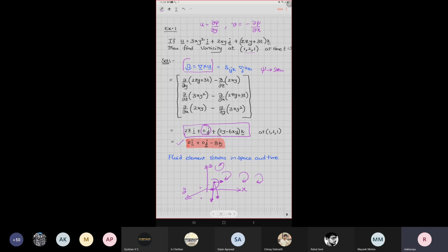Otherwise, unless I integrate throughout the field, I will not be in a position to visualize streamlines. Streak lines are more complicated to visualize and construct. Experimentally, they are so easy to construct. But if I would like to backtrack them, it is not that easy to do. At computer levels, plotting vorticity is much more user-friendly.